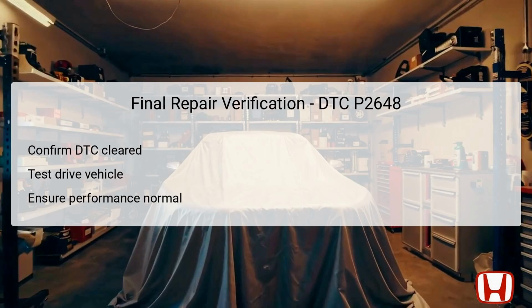Following that, it's essential to conduct a test drive under various conditions to monitor if the engine operates smoothly and without any related symptoms. This driving verification helps gather real-time data on whether the VTEC system is functioning properly and confirms that performance metrics are back to normal. Monitoring the vehicle for reoccurrence of the DTC during this phase will ensure all repairs are solid and no lingering